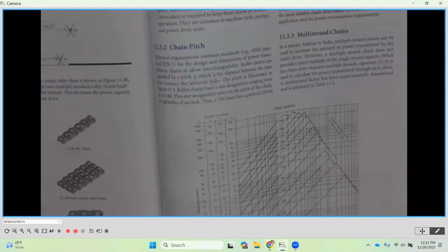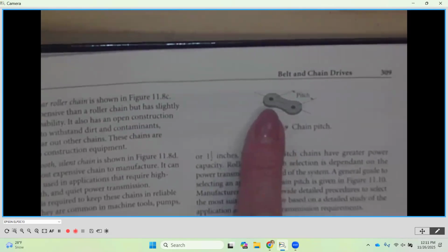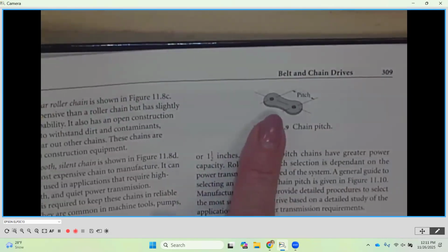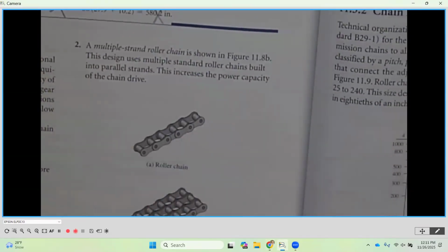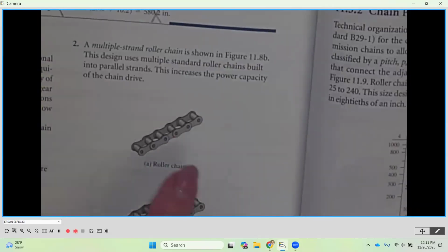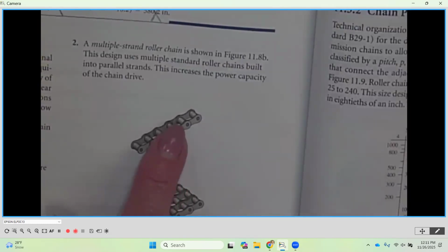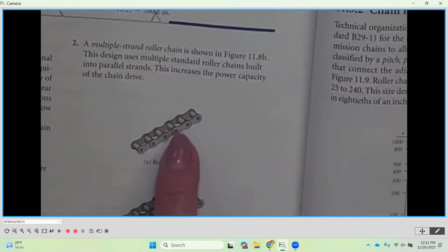If we look here, underneath, you're going to notice the side plate of roller chain, and that's this right here. It's one of the side plates pulled off, one of these side plates right here. If you notice how this is connected, we have these overlapping side plates, and they're called the side plates, and they hold the pins together on the roller chain. Now, as we look, you'll notice that the center of the hole on that side plate is going to join to the next roller.